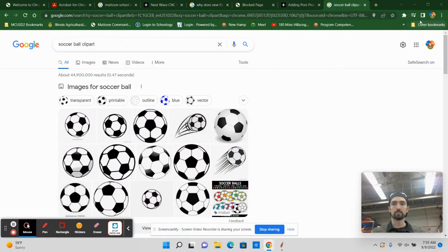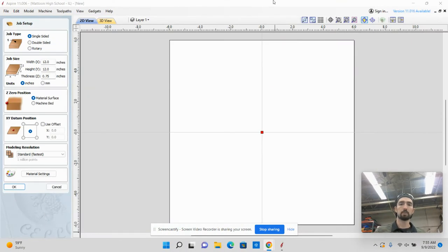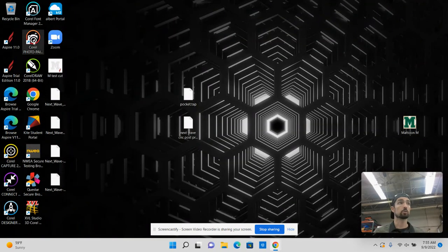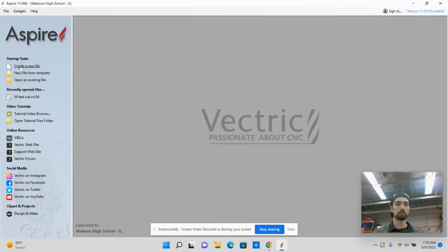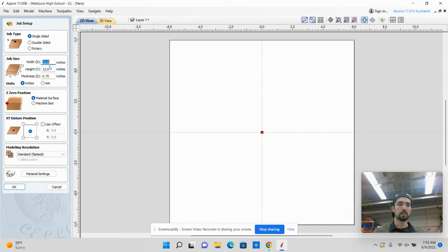Alright guys, this is a video on how to get started with using Aspire, which is used to create designs, cutouts, plaques, anything like that on the wood CNC machine. So we're going to click on Aspire 11. It'll pop open. We're going to click Create New File.